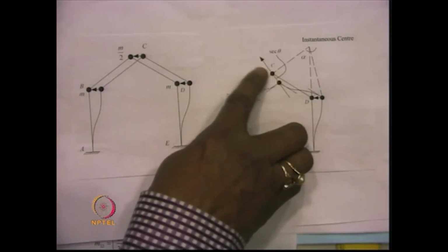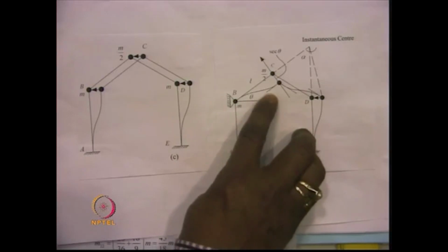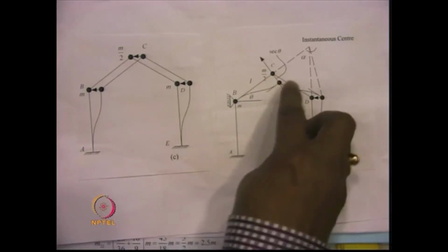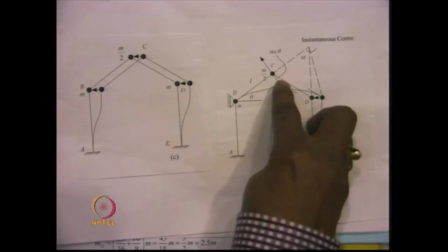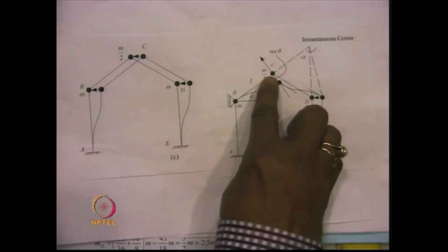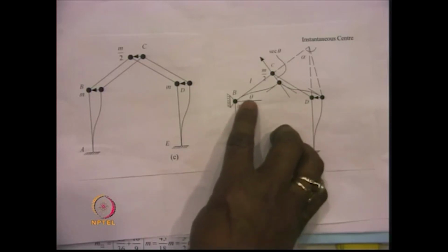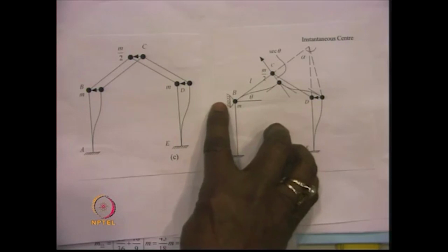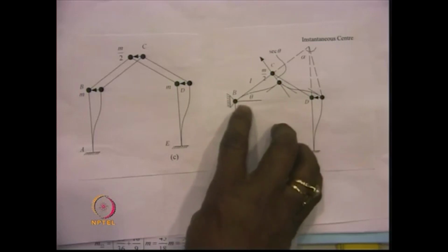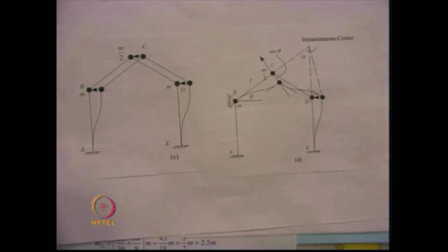The component of these two forces in the vertical direction by definition will be equal to m22, that is the inertia force developed at this particular point in the vertical direction due to the unit acceleration given to the crown in the vertical direction. And the component of the two forces which will be acting along this member is finally transferred to this point. The horizontal component of those two forces, when added together, will give the force which will be equal to m12. So, that is how one can find out the forces.